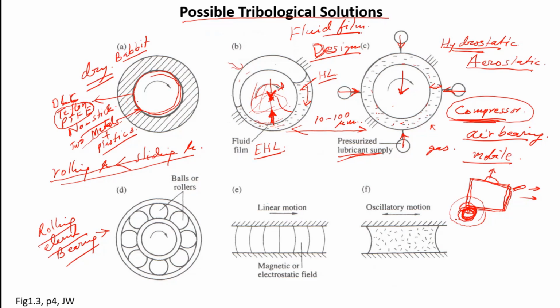Sir, can you give an example of dry friction lubrication, in which we use PTFE? Okay, so see, PTFE is very unique. Sir, the inner body is rotating, no? Sorry, what is your question? Sir, any example of this type of lubrication, dry lubrication? Dry lubrication, yeah. As I said, PTFE coating is provided in many of this kind of bearing. These are known as plain bearings.